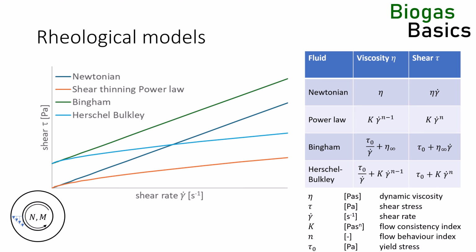This shear rate, shear stress diagram might look unfamiliar to many. After all, we are more interested in the viscosity, shear rate diagram. But in that diagram, all shear thinning fluids, that is power law, Bingham, and Herschel-Bulkley fluids, look very similar. It should be noted that there are many more rheological models. Leave scientists unobserved for too long, and they will come up with new and even more complicated models.